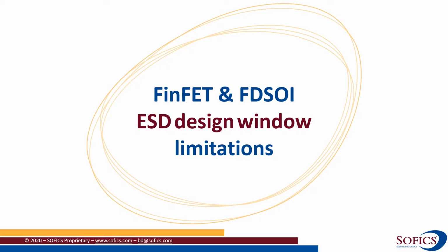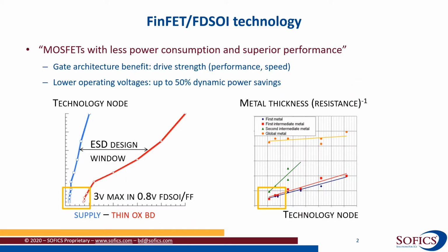I'm with Sofics. In this short video presentation, I will talk about FinFET and FDSOI ESD Design Window limitations. FinFET and FDSOI technology basically provides us MOSFETs with less power consumption and superior performance. Due to the gate architecture, we can have significantly enhanced drive strength. Further, due to the lower operating voltages, up to 50% of dynamic power savings can be obtained.